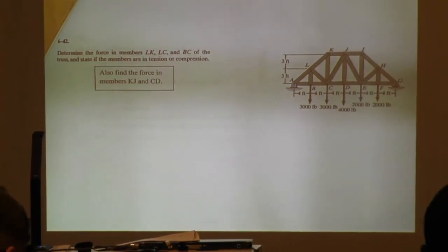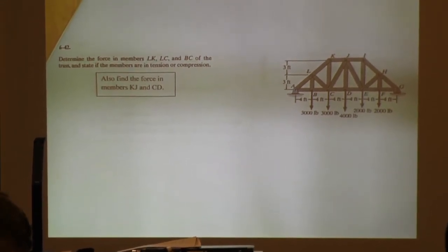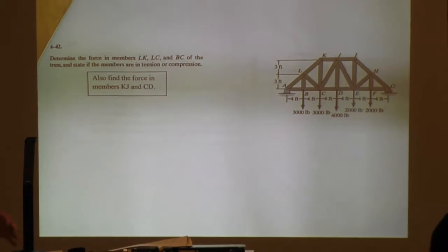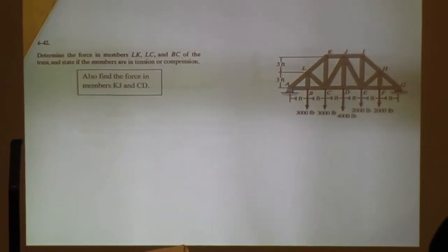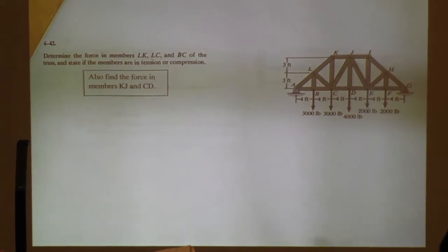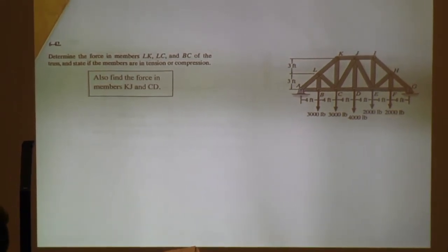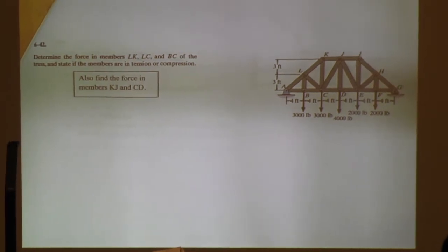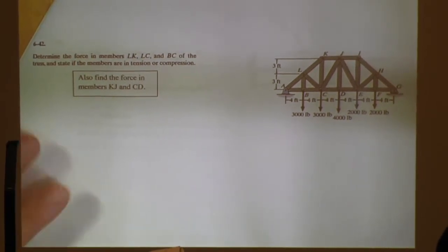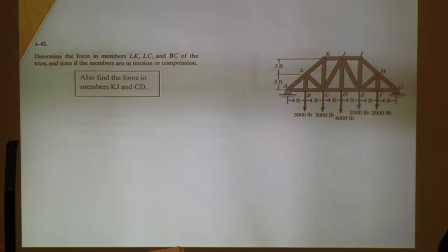All right. So in any of these truss systems, what's the first thing you should really look for? Well, you can do the members you need, but what's the very first step? And that makes the whole process easier if you find them. You got reactions before that. Zero force members. You get the zero force members, you just cut them out of the problem entirely because there's no force in them, right? So that's one less force.